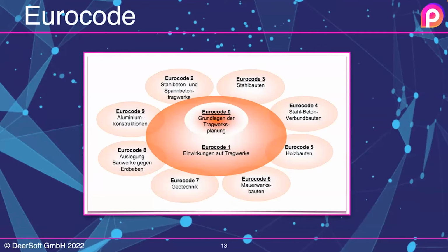There's one Eurocode for each of steel, aluminum, and timber structures. The main idea behind the Eurocode is that you calculate the impact and resistance separately and then check if the resistance is higher than the impact. The nice thing as well is that you can mix multiple materials. If you prove wood, steel, or aluminum, the impact is always calculated via Eurocode 1 and 2. You just swap in the other Eurocodes for timber, steel, or aluminum.